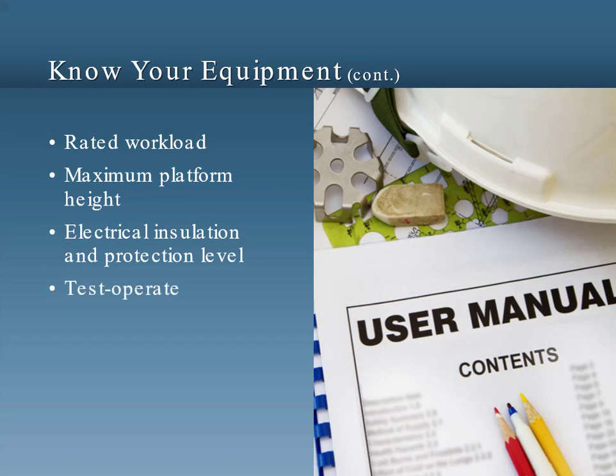Always be sure to test operate the aerial lift. Be sure you can operate it without jerky motions, which may cause accidents. Finally, be sure the aerial lift has drainage holes so rainwater does not accumulate. Be sure the drainage holes are not blocked. Think about the equipment you use. Are you familiar with all the safety issues covered in this and the previous slide?